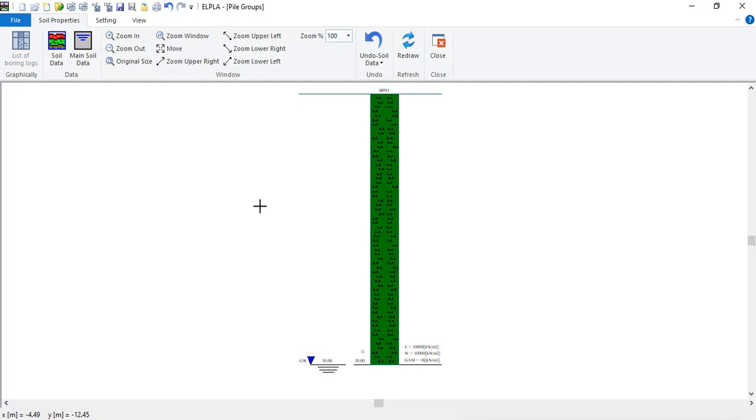To modify the label of the pouring log, double-click on the label of the pouring log. The corresponding edit box appears, allowing you to modify the label. Type P1. Press Enter to consider the label.